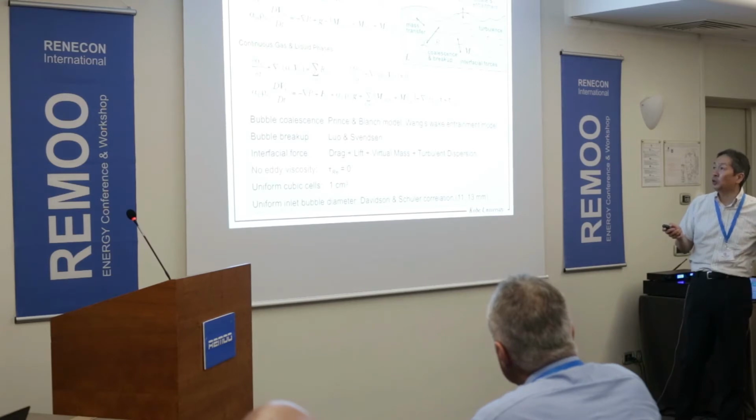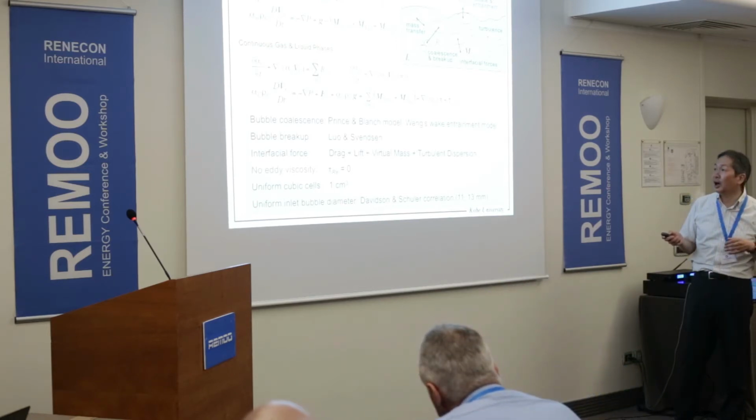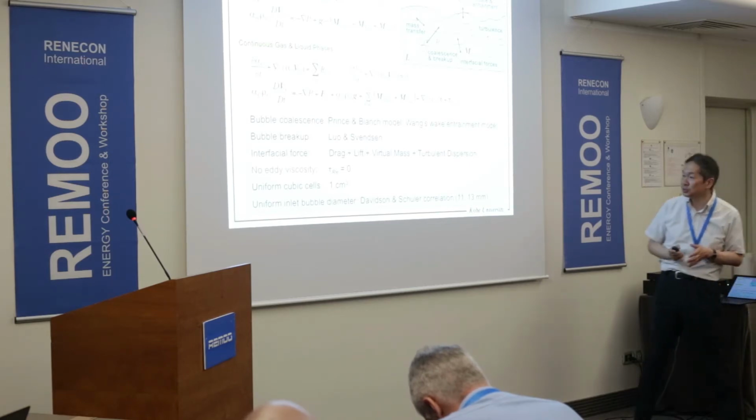And as Mike already told, we used a set of mass and momentum equations for the gas phases to deal with many bubble classes. We also take into account the presence of the interface, so we introduce the interface tracking method into these continuous gas and liquid phase equations.